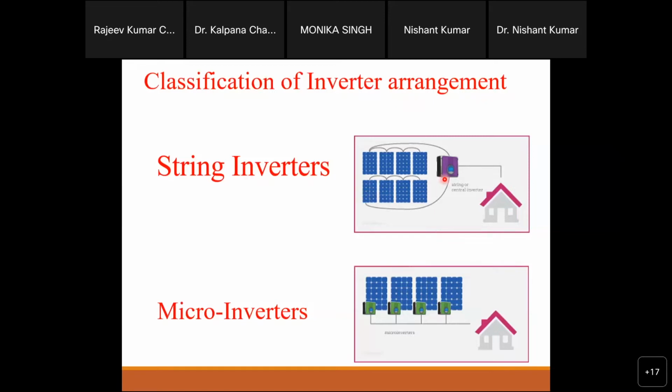So I will say the loss, first of all. One converter means we have a few switches, so here the number of switches is less, and you can say the losses are less here. Another thing is the control side: if you have one converter, you are going to control one, right? So all the control protection circuit, auxiliary power supply system, and everything will be required less here. But the demerit is this is less reliable.